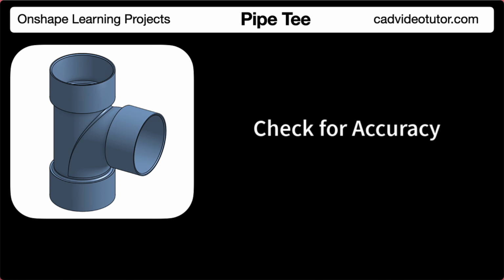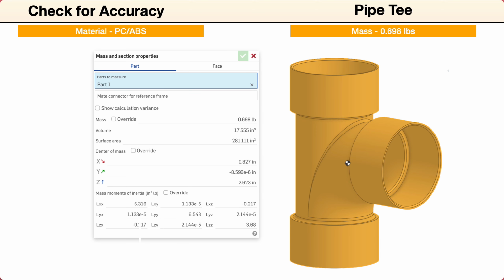In this segment, we'll check the accuracy of the model by checking its mass properties. To check the model, the mass units should be set to pounds and the material set to PC-ABS. If the size and shape of your model was completed accurately, the mass should be 0.698 pounds. Let's look at this process step by step.